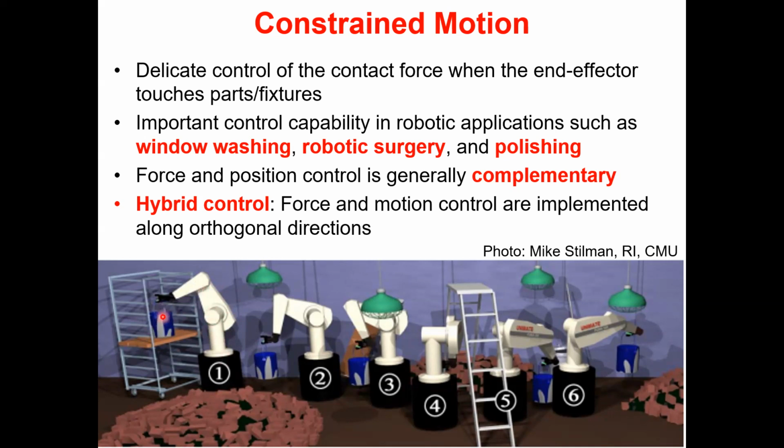And it takes this paint bucket from a rack, and there are bricks all over the ground. It's a constrained area, so you can't go there. It has to move, push back in this pose, and come over here, and then turn back, and go under the ladder to some other place. So this is a constrained environment, and the robot is actually handling something. So there's a force application. This is what is called a constraint motion. You don't have the full freedom to design your trajectories.